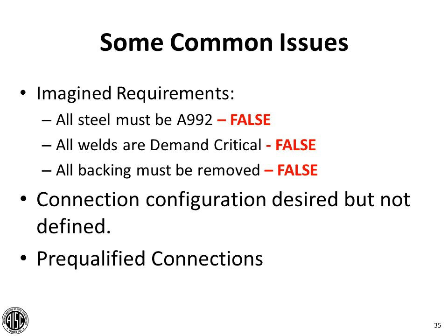The next two items there: sometimes people believe that all the welds on a seismic project, or all the welds within the seismic force resisting system, must be demand critical. That's not true. We'll talk about that in a little bit. And then, all backing must be removed is also not true, and we'll talk about why backing is sometimes left in place in a moment.